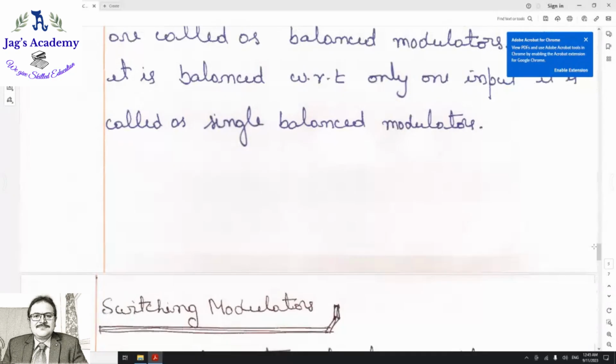Right. In modulation also you multiply by the carrier wave. In demodulation also you multiply by the carrier wave. So, this one device can do both modulation and demodulation. Hope you understood now. Right? That's why the multiplier modulator can be used in both modulation and demodulation, and this is called a synchronous detector. Synchronous detector. Okay.